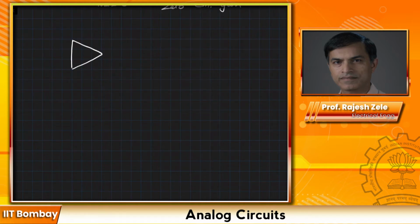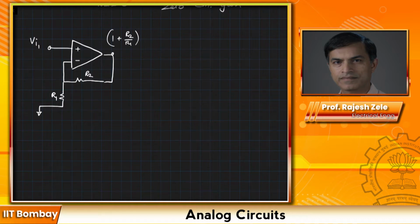So this circuit I'm going to draw a little differently. In this case I'm going to draw again a resistor like this, and then I'm going to say this is ground. Okay, so you can see here, let's say this is VI1 and this is R2 and R1. So you can see this is a non-inverting amplifier, and the gain would be R2 divided by R1 times VI1. All right, now I'm going to draw another non-inverting amplifier, which is drawn over here on the bottom.